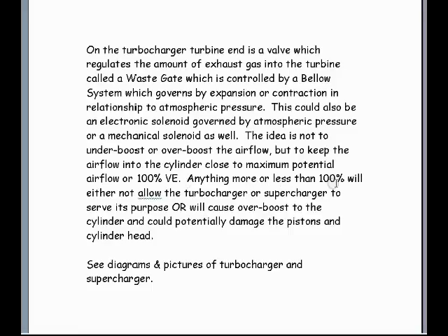Anything more or less than 100% will either not allow the turbocharger or supercharger to serve its purpose, or will cause overboost to the cylinder and can potentially damage the pistons and cylinder head. See the diagrams and pictures of the supercharger and turbochargers. So on the supercharger, since it's engine driven, you're going to have a regulation system on the output of the compressor side, kind of doing what the wastegate does with heat going to the turbine. So now let's look at the pictures.